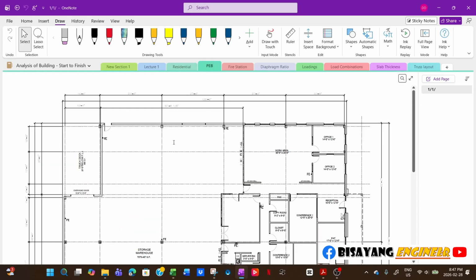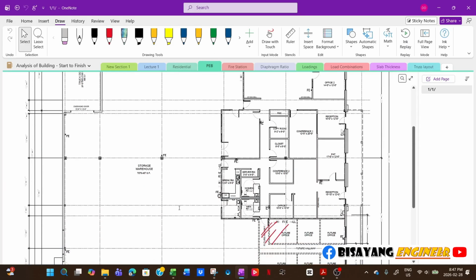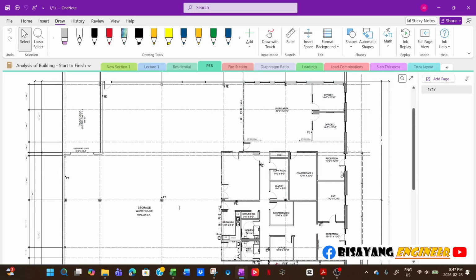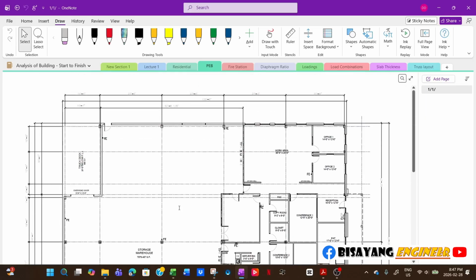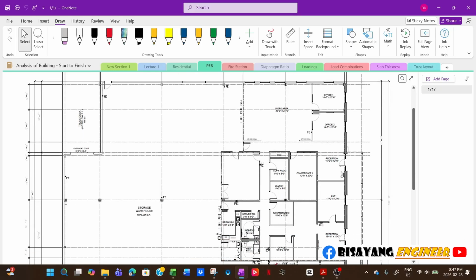Now I have another example here, but this is a large building. This is actually a warehouse, and this was one of our old projects in the US. This is a pre-engineered steel building, but we will try to lay it out with wood frame and steel. The way it is laid out, with fewer columns, I don't think a concrete frame will work on this one. I mean, it can be done.